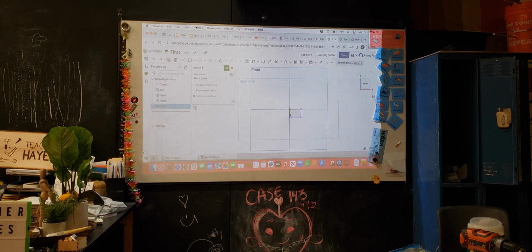All right, so let's get into measurements and dimensioning. So let's create a simple line. Let's click on the origin and then drag out a line. Make it at an angle, just kind of like how it is. Yeah, okay. Just click again to make a line, and then click escape to get out of the line tool.